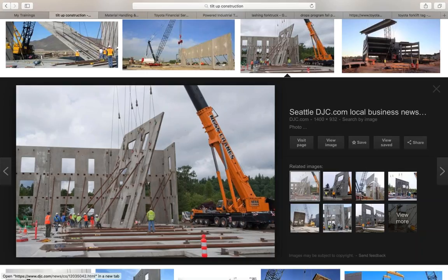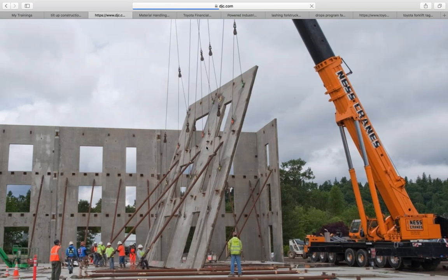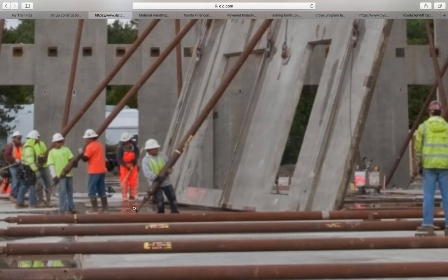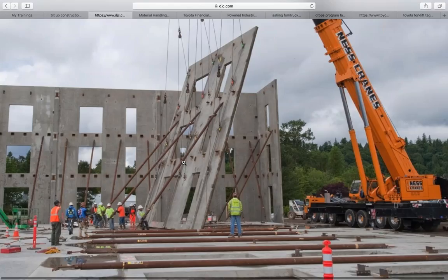And then once placed, the panels have to be braced in accordance with the manufacturer's instructions. If you look at that photo on your right-hand side, that's what that is: two braces. They look like pistons or shafts kind of. Those are braces. So when the panels go up, they're going to be braced in place, just like in the picture. If you look here on the computer, there you go as well. There's another illustration of these braces. Okay. So of course, look how close these employees are getting. There's a risk of these employees being harmed. But look how many different anchor points that tilt-up construction wall has.